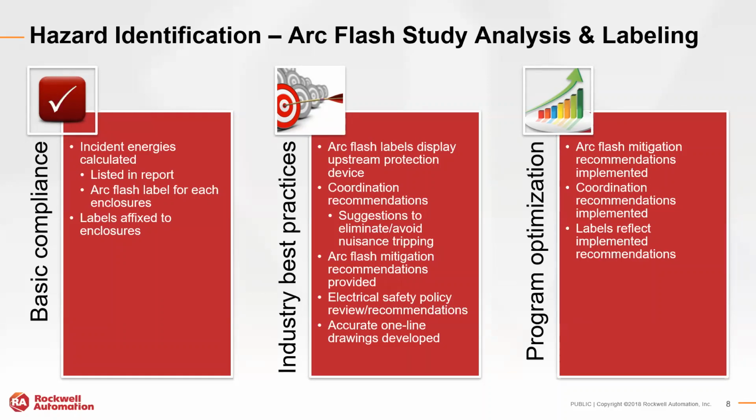Well, then you want to document with the arc flash provider that you use to do the study to provide mitigations for equipment to reduce it to the less than 12 cal per centimeter squared hazard, so that energized work can be prohibited when needed for that equipment.